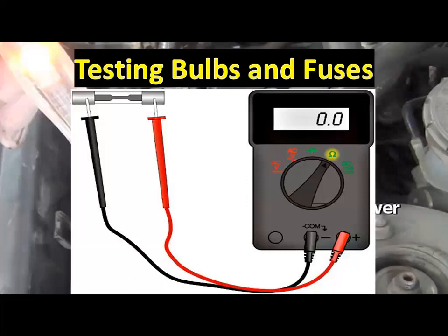So to summarize, high charging voltage may cause the headlights to become excessively bright when engine RPM is increased. High resistance in headlight circuits reduces current flow and causes dim lights. If only one headlight is dim, the ground circuit on that light likely has high resistance. Measure the voltage drop in the headlight circuit to check the circuit resistance.